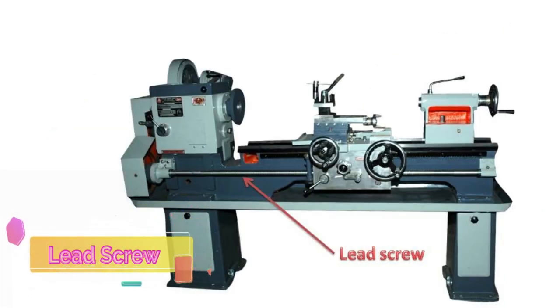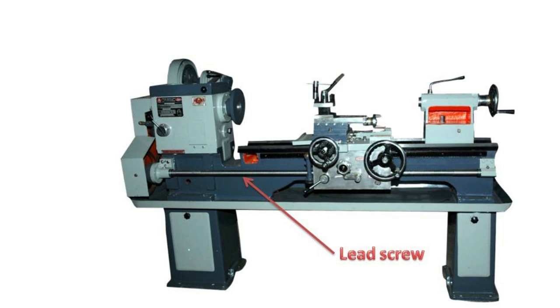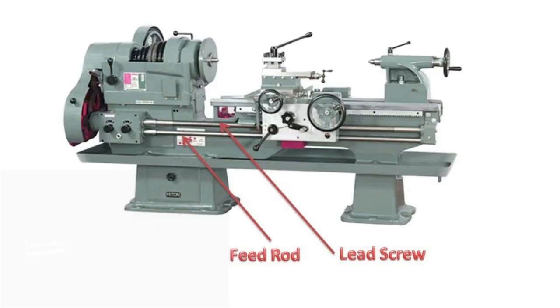Lead screw is a screw rod which runs longitudinally in front of the lathe bed. Lead screw rotates by the help of the same motor which is used to rotate the spindle. Lead screw rotation moves the carriage automatically in longitudinal direction.